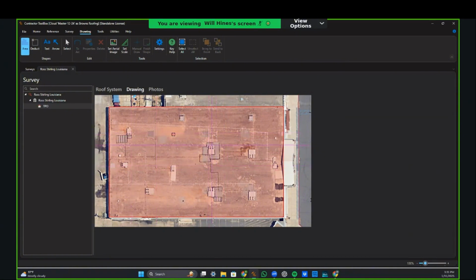I will say too, the nice thing with setting a scale is that the units on this are super, super visible. So if you're using a rectangle deficiency and you don't know the exact size of this, like our curb flashings for re-roof estimating, which are set up as rectangle deficiencies, you're typing in a width and length and a height. That width and length will be relative to the size of the square that you have on the drawing. So it's actually a little bit of a cheat way. You can figure out what size units you have up here and account for the right materials.